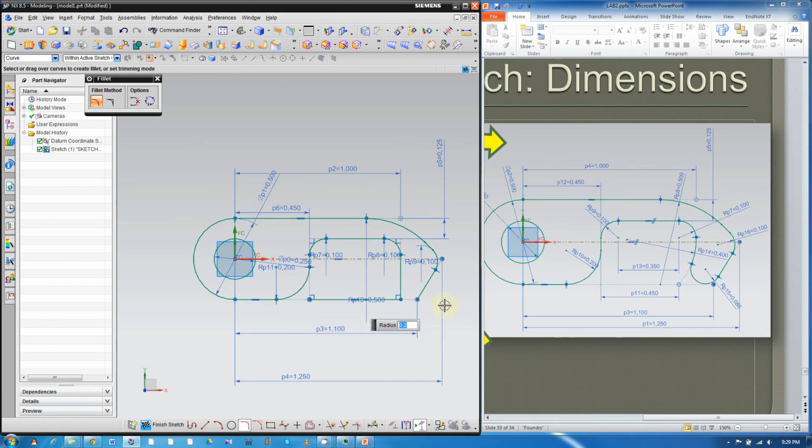Basically, we need an arc here, then we can do a fillet. As you can see, the arc on this side is 0.4 in radius, and it's on the bottom straight line. So we can use this command, arc, and most commonly used is this 3-point arc.